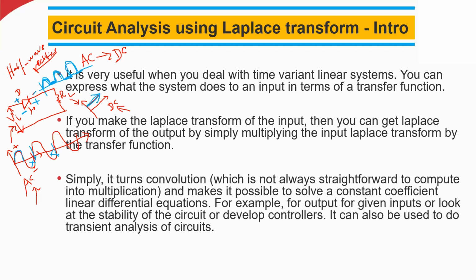So what I wanted to tell you here. Now I have to calculate the output DC voltage. So how can I calculate that? I need to find the average of all these pulsating DC voltages. For example, now I apply plus 5 volt and here minus 5 volt. So minus 5 volt, I don't care because I don't get any output. This plus 5 volt I am getting here. So plus 5 volt, plus 5 volt, plus 5 volt.